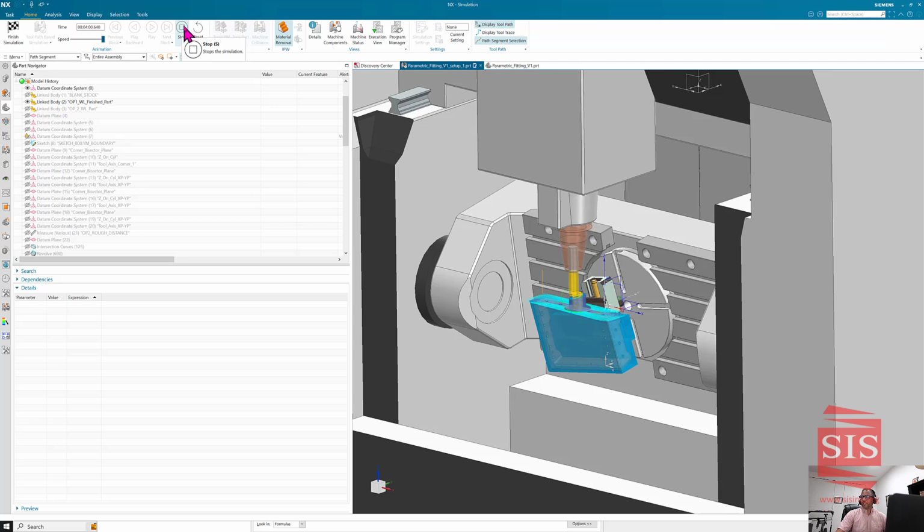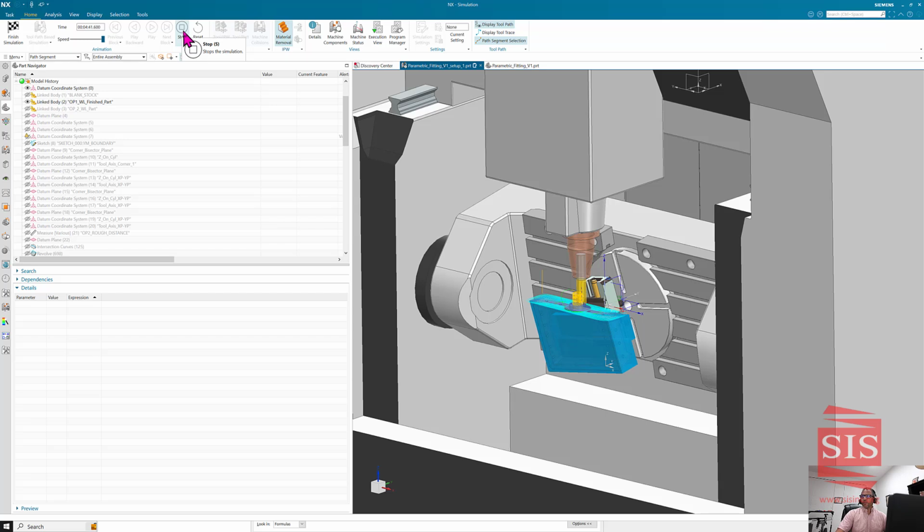Basically, in this adaptive roughing operation, I didn't want to leave any thin walls. So essentially, I use the pillar cutting option in NX to cut until some size pillar that I want, and then helically go down and remove that pillar. That way, in this high-speed machining strategy, you don't have any thin pieces of metal that will be ringing or could possibly damage the tool.